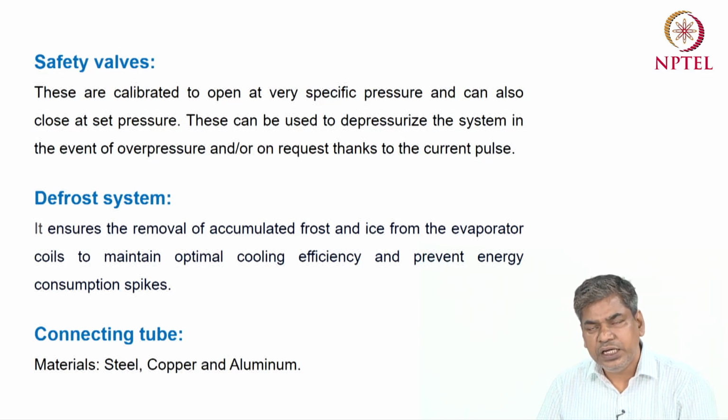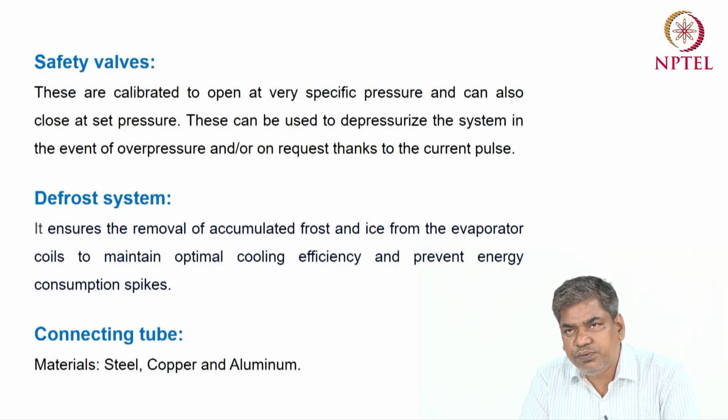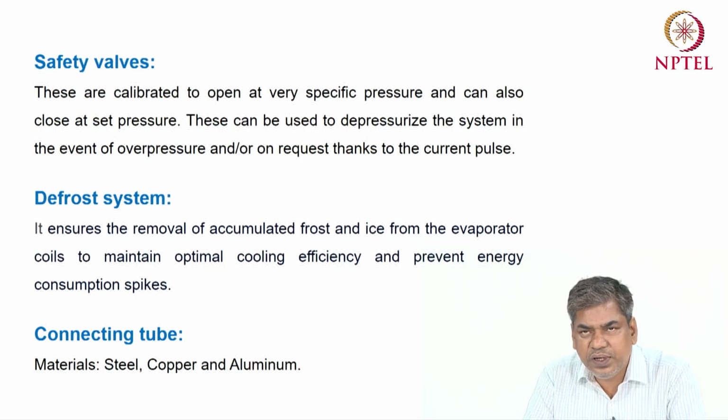Okay, so that ice will create some extra resistance for the evaporator heat exchanger, for the evaporator heat transfer. So the ice formation on the evaporator tube or on the evaporator plate, whatever it may be, will create extra resistance for heat transfer, and that will degrade the performance of the evaporator.